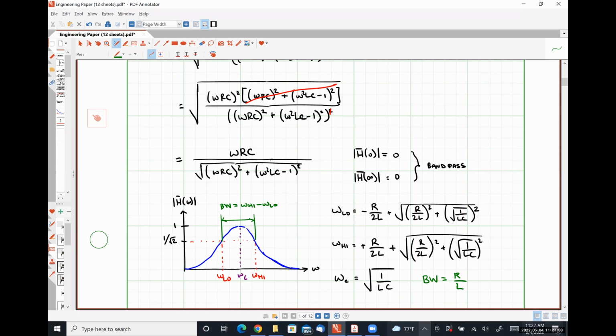FM radio stations have center frequencies that occur at like 89.1 megahertz, 89.3 megahertz, 89.5 megahertz, et cetera, right? So those are all the center frequencies. And then the bandwidth is effectively just the channel separation. So the difference between 89.1 and 89.3, et cetera. Excuse me, they have center frequencies at some number of megahertz with a bandwidth of 200 kilohertz.